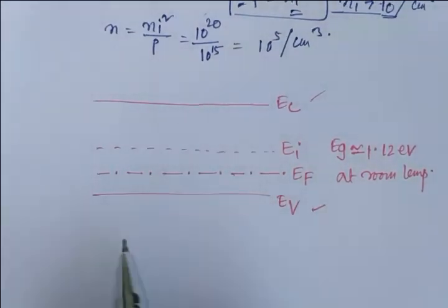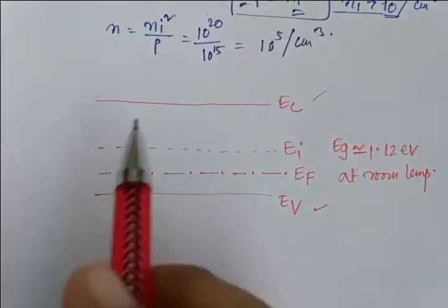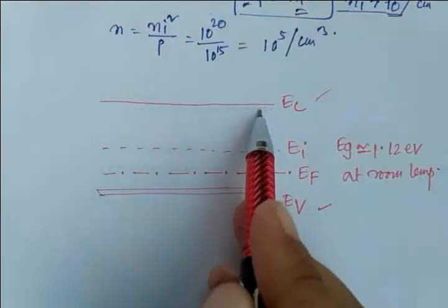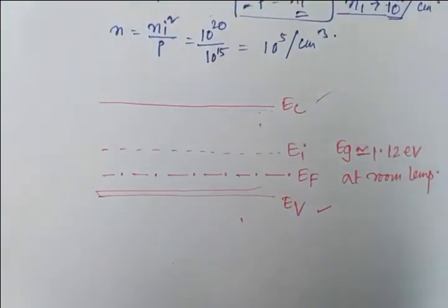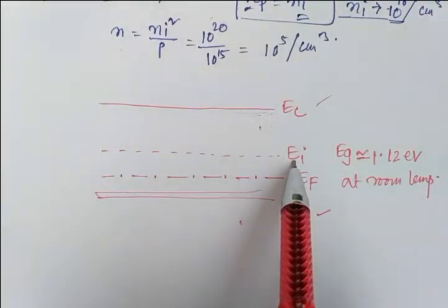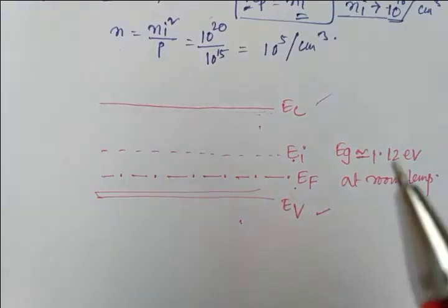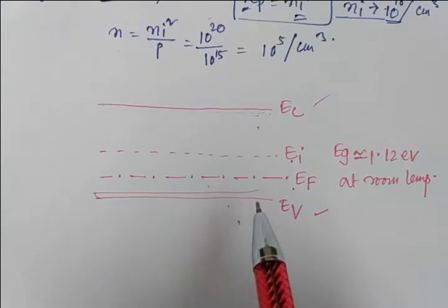Okay, so from this drawing, how can we define it? Here, these two parallel lines I drew first are the indication of the semiconductor. Then, if there is no doping, there is an intrinsic energy level. The position of the Fermi level, based on p-type or n-type, is like that, in the lower half of the band gap.